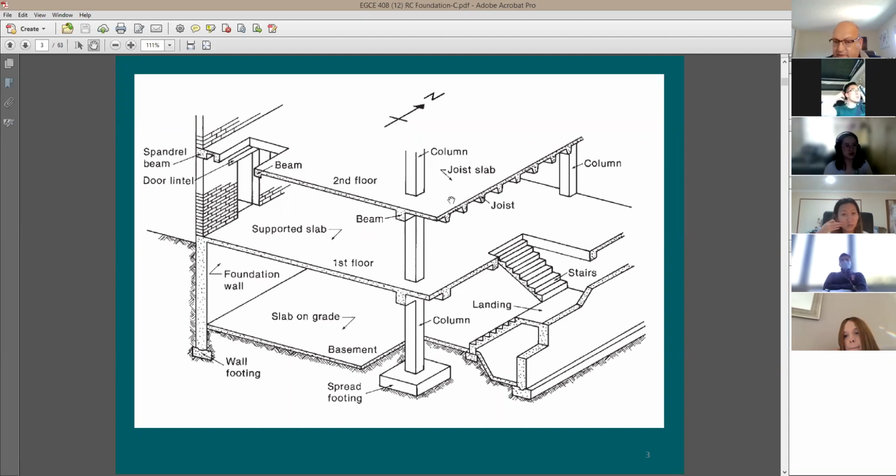So what happens, load is going to be transferred through the column, goes all the way down, and then after that it's going to be supported by the footing, and the footing is going to be touching the soil. So this interface between the soil and the footing is going to be exposed to vertical stresses, because the load that you're talking about here is all about vertical loads, and again, some moment that comes on the top of it. So when you have the vertical load coming downwards, all the pressure is going to be acting upwards from the soil itself.